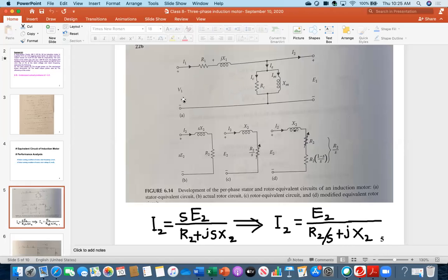So everybody look, we are applying the voltage to the motor, to the stator, current flowing is I1, and R1 plus jX1, this X1, that is the actual coil on the stator circuit. This is kind of a per phase circuit. It is the same for the three phase, just it is treated one phase at a time. So R1, and then every coil has some sort of resistance, as I already mentioned, which is R1.